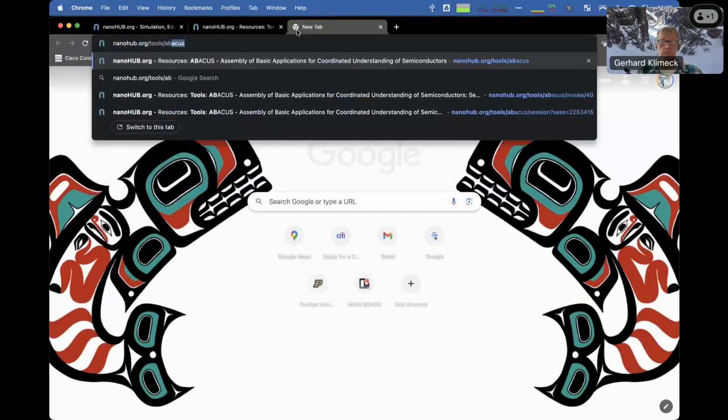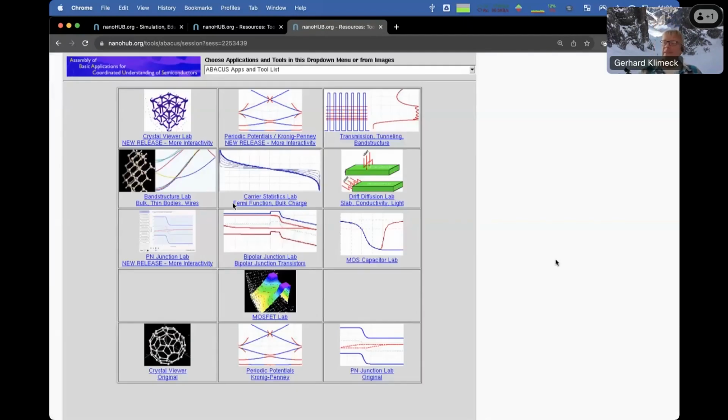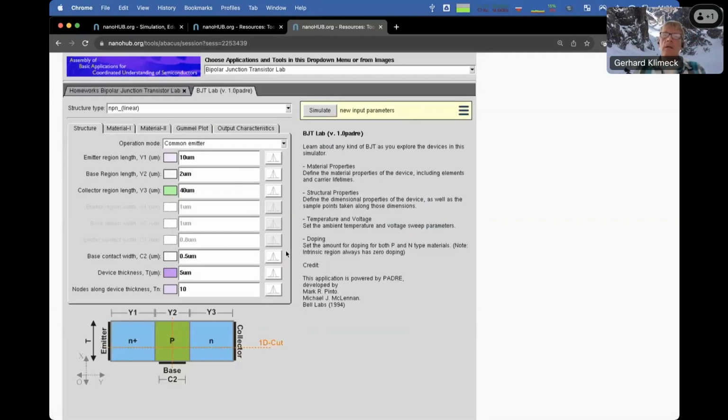All right. Someone asked, where are BJTs used in current electronics? Typically still in antenna circuits. In your cell phone, there's probably an HBT in there, which is a heterojunction bipolar transistor. And in linear amplifiers, I believe there are still BJTs in there. And in some very high speed applications. Yeah, I'm not going to go out on a limb, but certainly on those items.